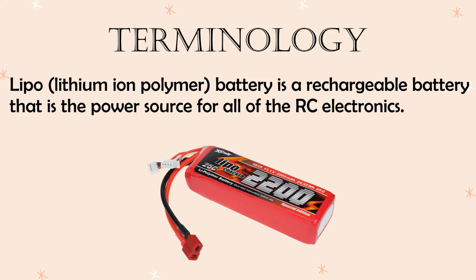How do you power up the electronics? You need a LiPo battery, or more correctly, a lithium-ion polymer battery. LiPo batteries are generally safer and more environmentally friendly when it comes to RC systems. They are pretty lightweight, have good performance, and are also rechargeable. In general, we should try to make our model airplanes as light as possible to increase the efficiency in the air and also to reduce the load on the motor.